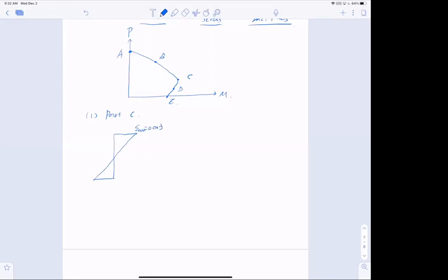Now the steel, on the other hand, reaches the yield strain, which is epsilon s equal to epsilon y equal to 0.00207. Why do I know this? Because it's grade 60. And now I just need to find the compressive zone C and then determine my Fs prime, which is the stress in the steel. But to know that, I need epsilon s prime, which is the compressive strain of the steel.